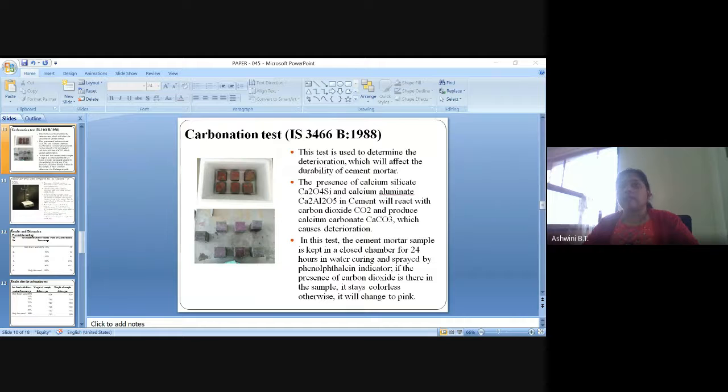The compressive strength of the cement mortar cube for 20% normally exceeds and is similar to the river sand. The fresh mortar, with an increase in the sea sand, gives good flowability compared to the river sand. The chloride content increases with the sea sand percentage, which leads to higher corrosion, and the strength and durability decrease.